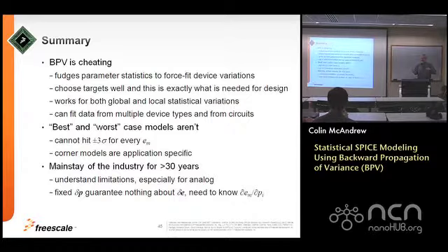Okay, so you actually do a lot of simulations, and you do it for all the outputs. Yeah. If you have 5 parameters, you have to do 6 simulations because it does a perturbation in each dimension for the parameters and then calculates the sensitivity. I didn't say this, but you notice that it's linear and things happen to be nonlinear. There is a nonlinear extension to this, but we don't actually use it in practice.